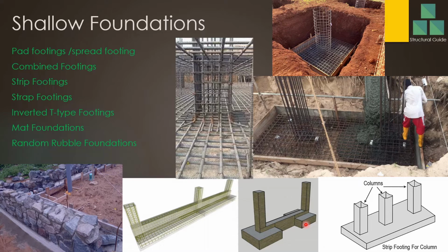Therefore, we have to place the foundation at the edge, and the footing cannot continue like this here. So in such situations, we want a footing like this. We may avoid the spread footing in some cases. We have to check the pressures and eccentricity, and then sometimes there are possibilities of avoiding this strap beam. That has to be decided at the design stage.